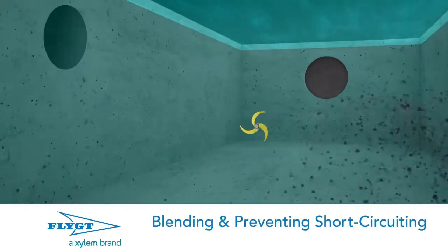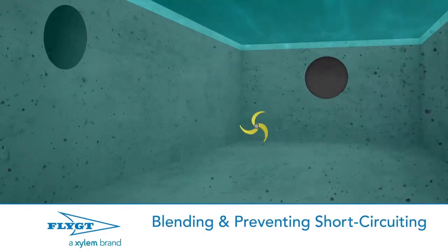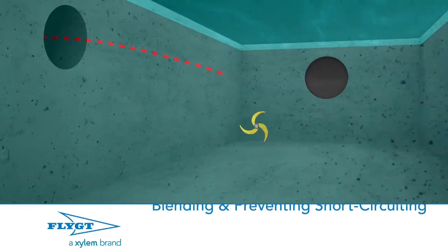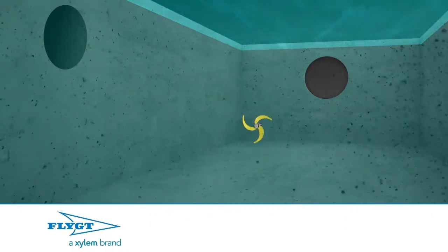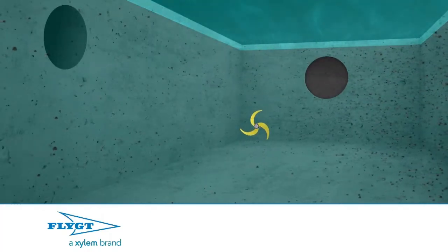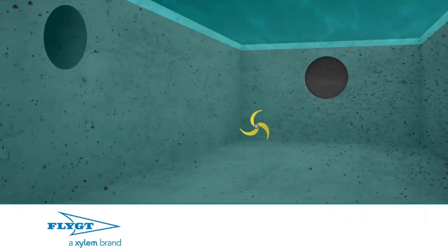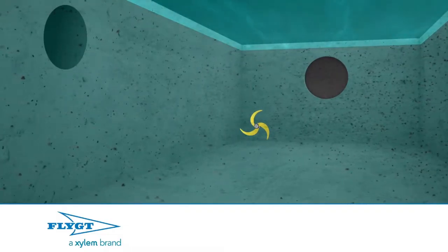Finally, to effectively blend and prevent short-circuiting, we must create a homogeneous mixture given a continuous inflow and outflow of fluid. Otherwise, the incoming fluid could pass quickly through without mixing thoroughly with the fluid that is already in the tank, or staying long enough to achieve the desired reaction. Whatever your mixing needs, a clear understanding of mixing duties will help you define the intensity of mixing you require. With that information, you can then choose the appropriate tool and settings for the job.